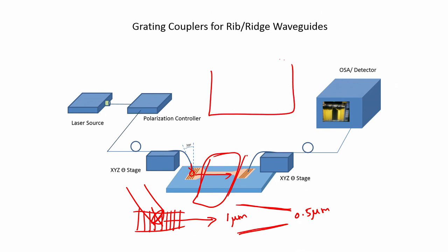If you want to measure the loss of the waveguide, for example, we can consider fabricating different lengths of the waveguide on the same substrate, and say for example from here to here is one. I will make another smaller waveguide, and the loss differences can be measured. For example, this is an extra length, L and L dash. So, the propagation loss for the extra length will be estimated by measuring the output optical power.